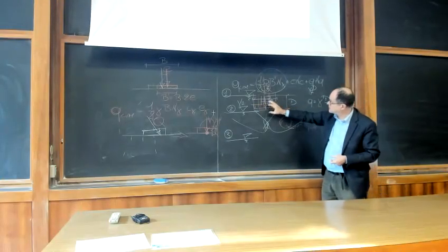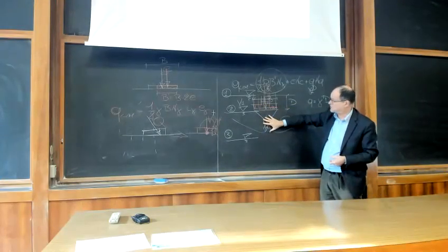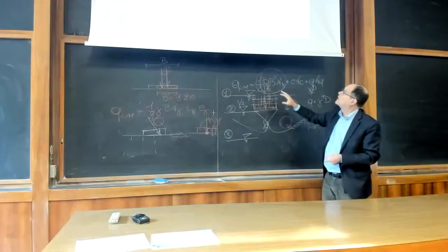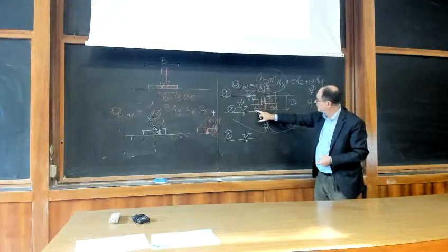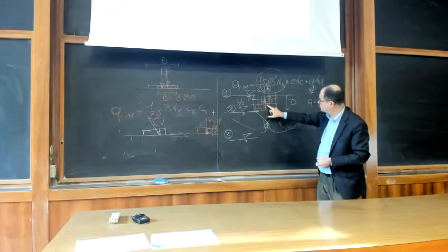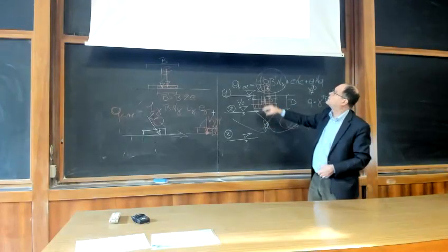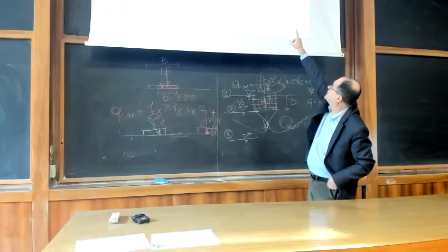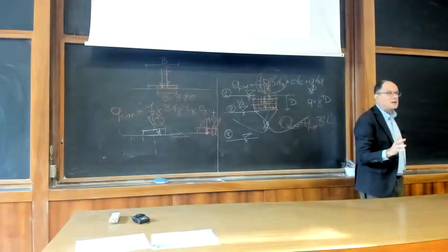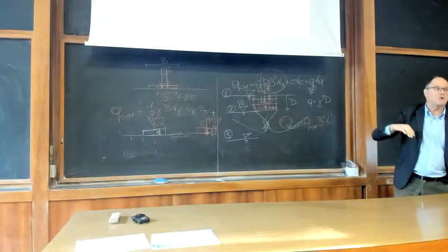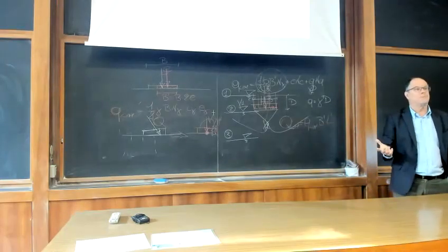This is a different mechanism with respect to this. And so the sliding mechanism will be controlled by the friction between the footing and the soil itself, which is the inclination of that sliding line. But this blue line is in the case that there is no interaction between horizontal and vertical components.